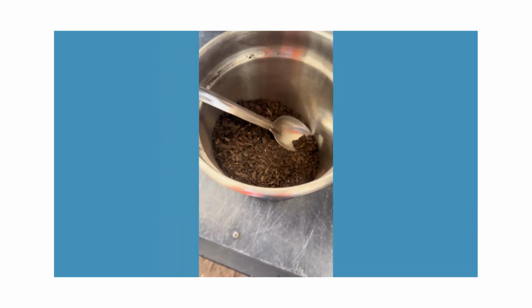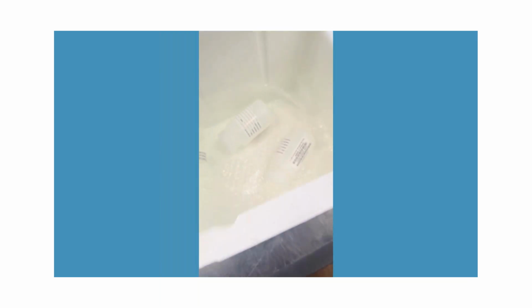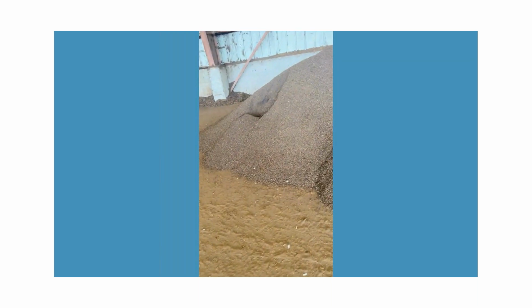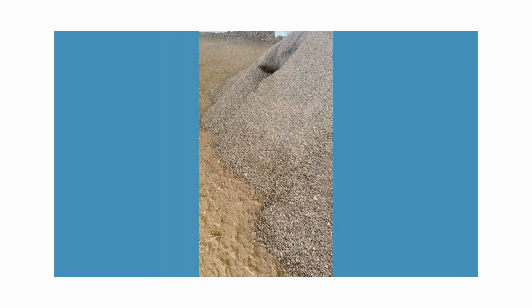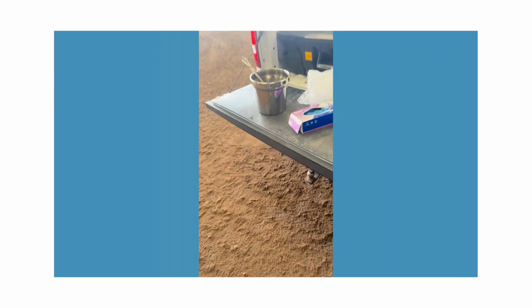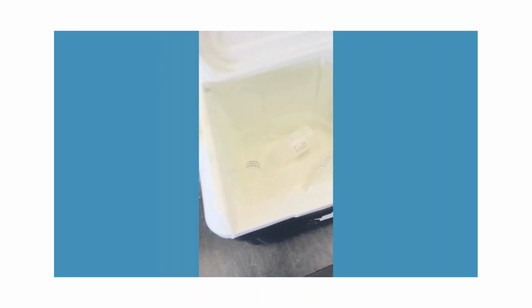Biosolids monitoring. What I did was a grab composite. Here are my sample bottles. I haven't opened them until I'm ready to fill them. I go around my biosolids pile and do a grid all the way around the perimeter of the pile, digging down below the surface about a foot or so and getting a core sample grab from each area, and composite that, then mix it and put it in my sample bottles.